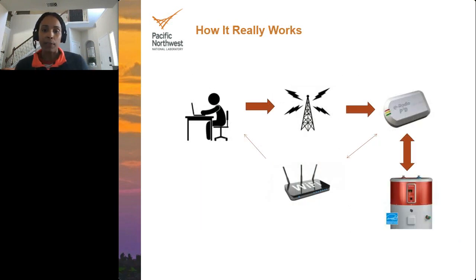I believe they've explained in the previous presentations how the CTA works, but I'll just briefly go through. In our field study, the water heaters were already installed with the CTA 2045 ports. Then an aggregator like eRadio would provide a universal communication module so that we can communicate through RF or Wi-Fi. And once that's installed on the water heaters, we can start to send curtailment commands or load up commands to control the water heaters based on the objectives or the desired times.